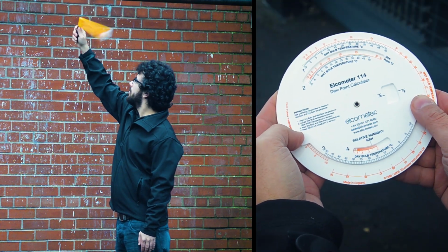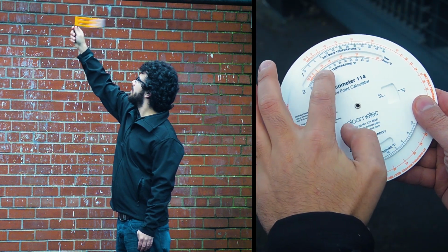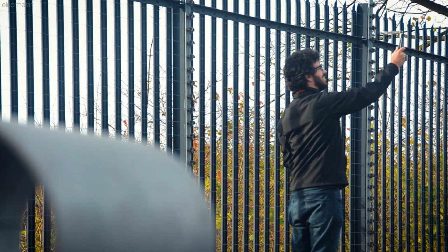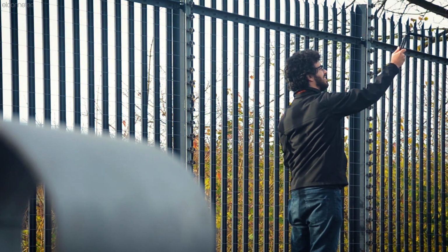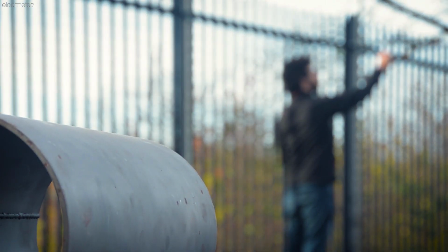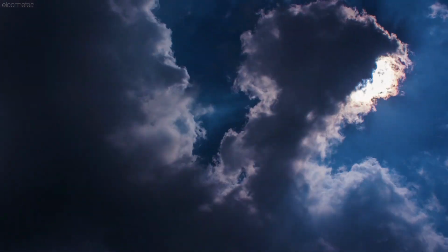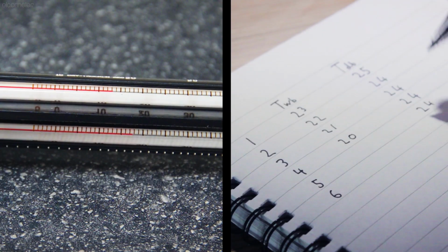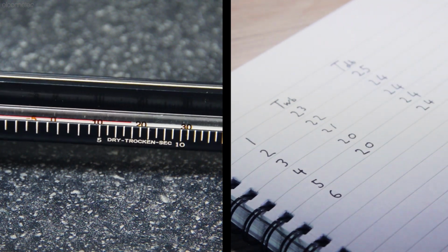While this method has been long used in the industry for monitoring climatic conditions, it does have some disadvantages. For example, whilst whirling hygrometers provide a good indication of atmospheric conditions, due to their design they can't provide the localised conditions at the surface of the substrate to be painted. Also, environmental conditions change whilst the paint is being applied, and this is not the most convenient of methods to continuously repeat to ensure conditions remain acceptable, as it is quite time consuming.